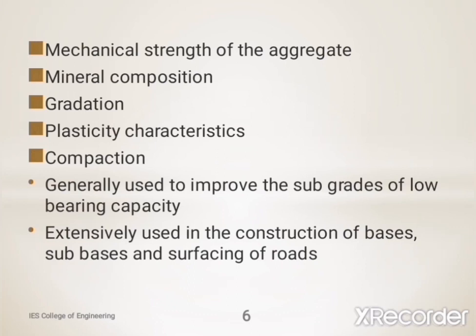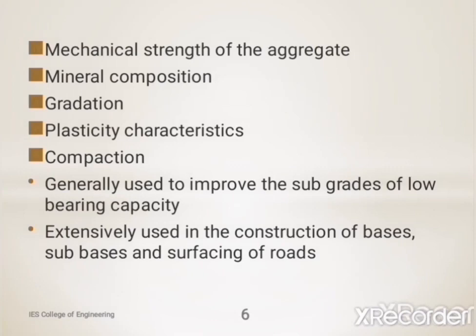And the third factor is gradation. The gradation of the mixed soil should be such that the voids of the coarser particles are filled with finer particles so that a high density is obtained, thereby we get proper gradation.